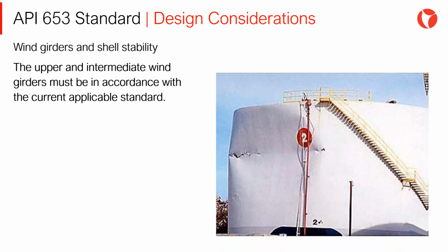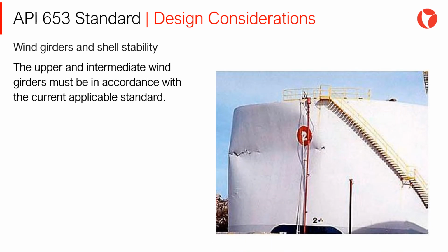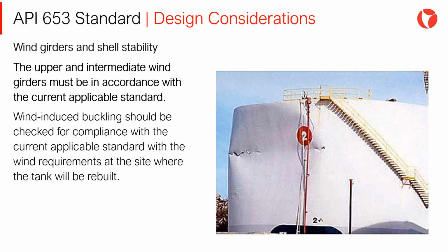As for wind girders and shell stability, the upper and intermediate wind girders must be in accordance with the current applicable standard. Wind-induced buckling should be checked for compliance with the current applicable standard with the wind requirements at the site where the tank will be rebuilt.